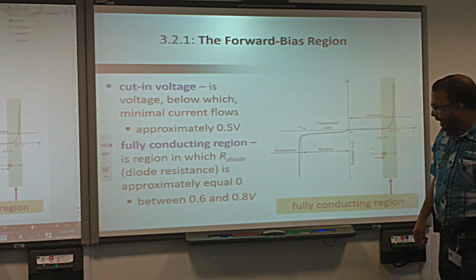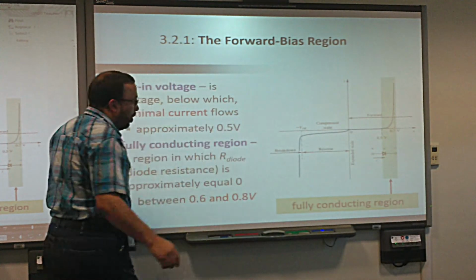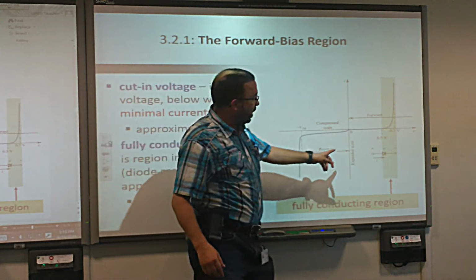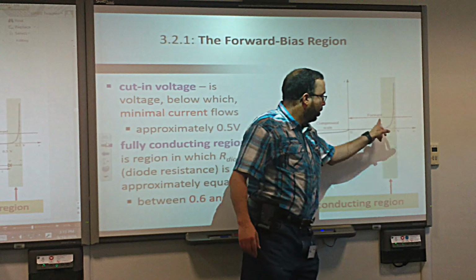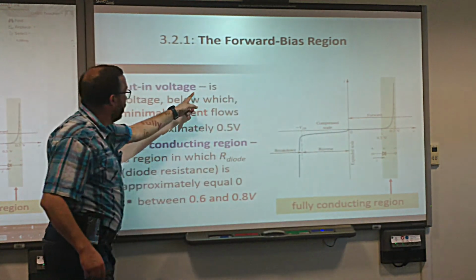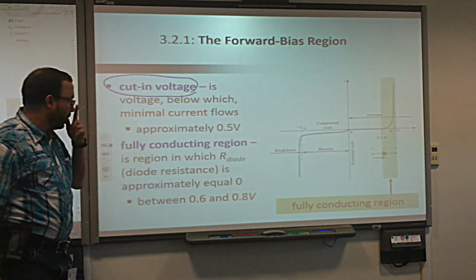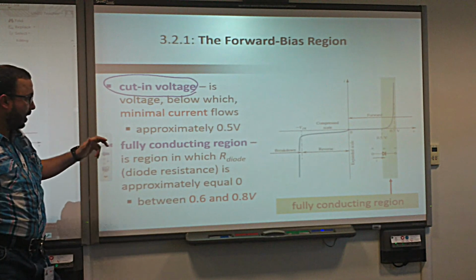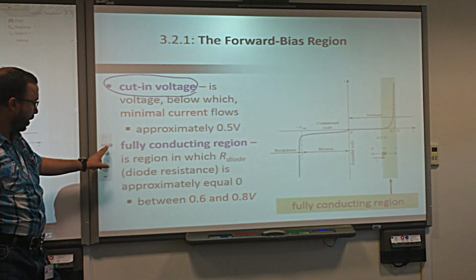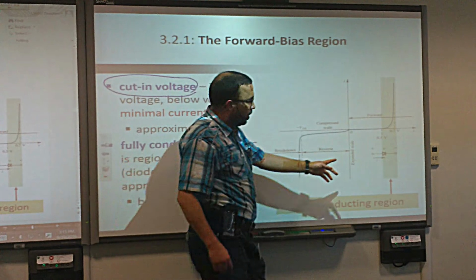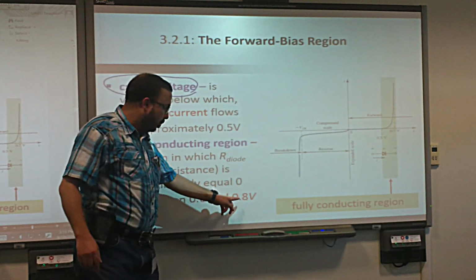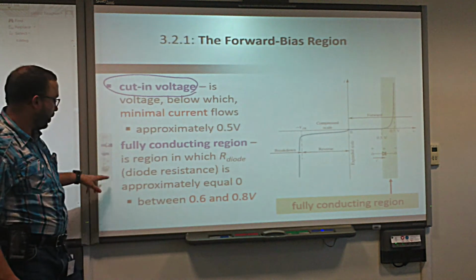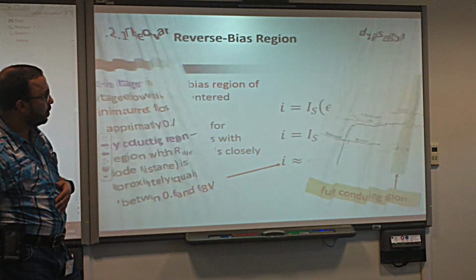Okay, please switch off the thing. Now we said something else before. We said that the real diode will not start from zero. Actually, it starts from a certain voltage. We call it the cut-in voltage, or the threshold voltage. This threshold voltage is typically between 0.6 volt and 0.8 volt. So it's not huge.